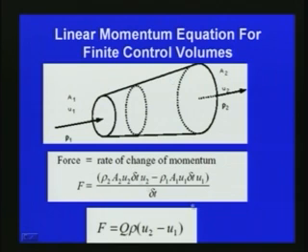After simplification, we can write the force is equal to Q, where Q is the discharge passing through this pipe. Q is constant, due to the conservation of mass between section 1 and 2, and if you assume the density rho is constant, we can write rho 2 is equal to rho 1. So, F is equal to rho Q into (U2 minus U1), that means the velocity difference between section 2 and 1.